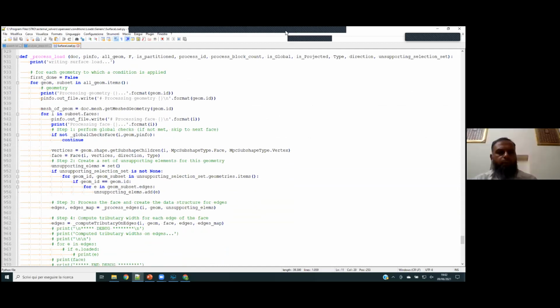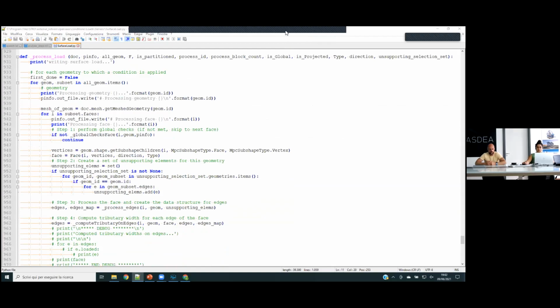So for shell, we will use this one? No. For shell, you have to use face forces. Face forces, okay. Yeah, because for shells, that one is also an automation that we have in STKO, because a face force is a pressure, so a load per unit area. You apply it on the surface, and then STKO will compute the equivalent nodal loads doing the nodal lumping. So for the same reason, basically, because in OpenSees you don't have a surface load.